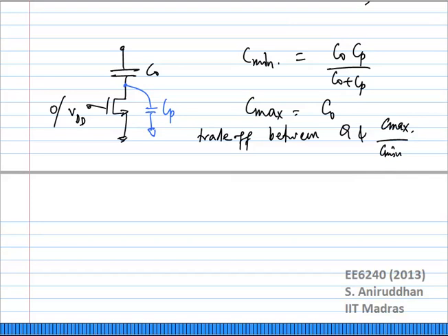And different people have found out ways to optimize this such that it works. You get the maximum Cmax by Cmin for a given Q. You can look up the literature or look at what other people have done. But there are many ways to implement this. Since you have a differential oscillator, you can have two single-ended capacitors and switches. You can have a differential switch. Okay? But now you need to bias the center point. Depending on how you bias it, the parasitic capacitance will change. So when you design your VCO, you can look at all of these methods of optimizing the capacitor bank also.